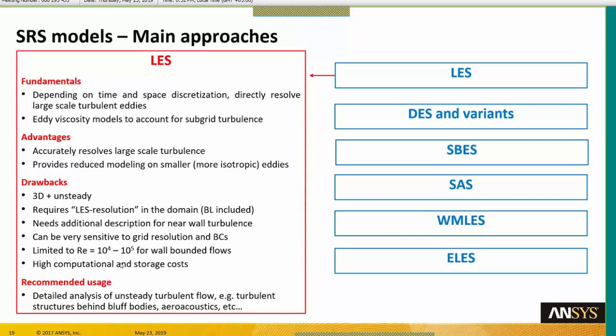And when you say transient, that means you will have several snapshots of the spatial fields of the quantity, which means a large number of solutions. Whereas for a RANS calculation, usually it's nice to have only the converged solution, which makes one, compared to a large number, because with LES you want to animate the flow to see its unsteady characteristics.